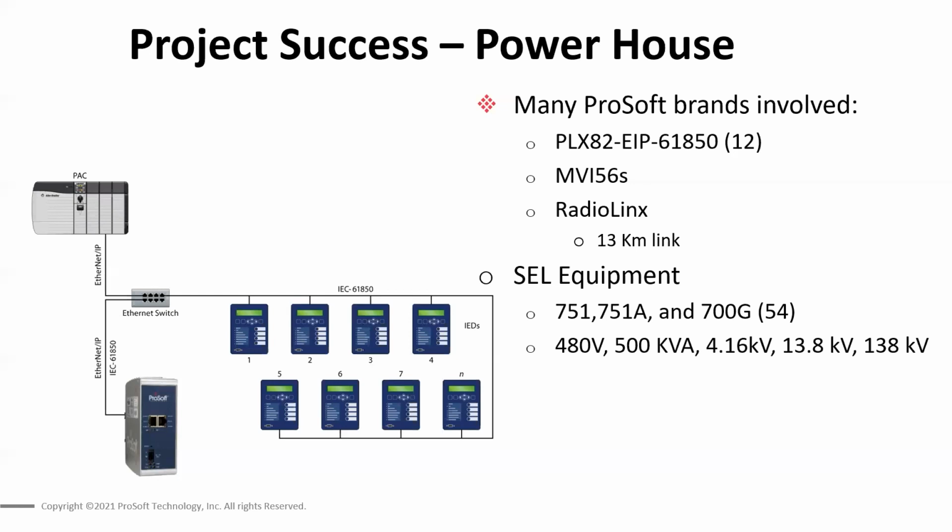So as we release the upcoming ControlLogix module, we'll have even more information to provide you on the performance that you can expect. But really, 4 millisecond I/O connections is what allows us to say that you can get 4 to 8 millisecond Goose publisher messages out to a device.